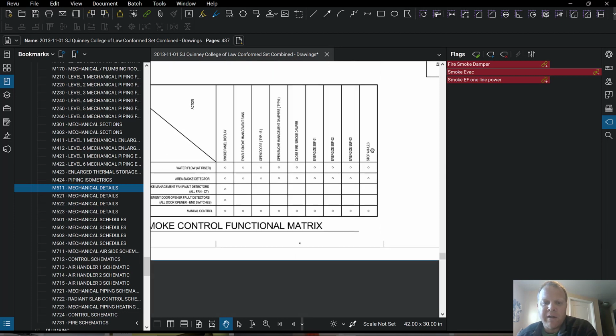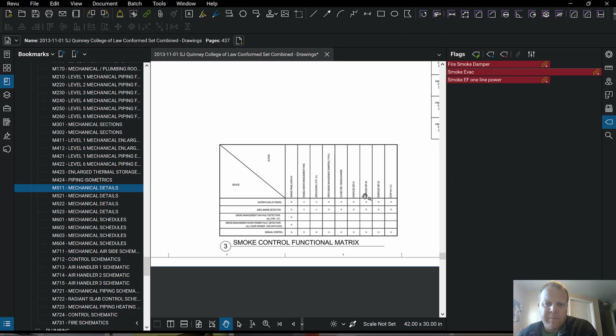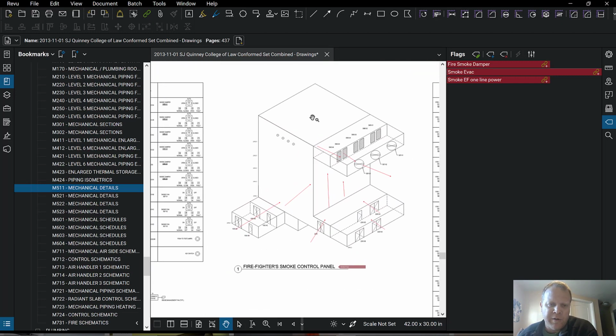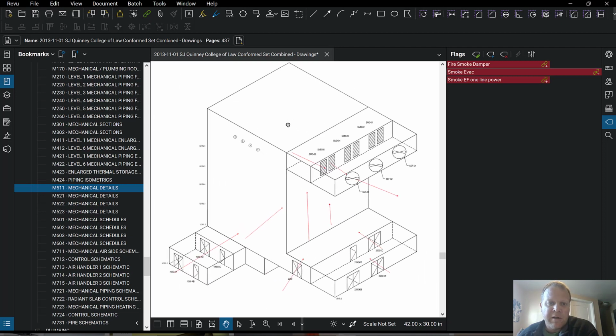Why do they not want the air handlers to run? Well, going back to this space, remember, I don't remember what all this building was as far as HVAC. But an air handler is going to get some return air on it, right? And so they do not want to pull smoke or hot gases or whatever from one space into the ductwork, which would allow it to transfer to another location, right?